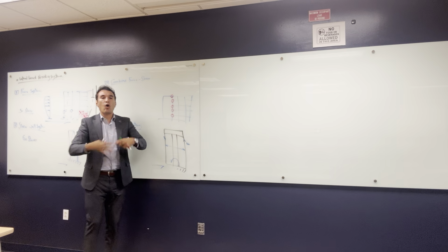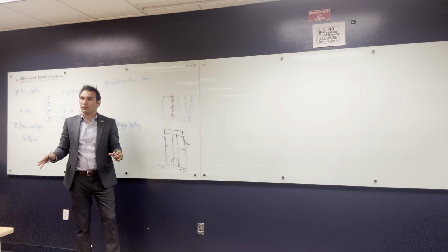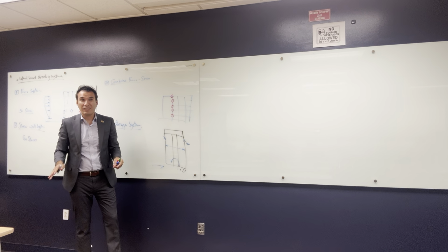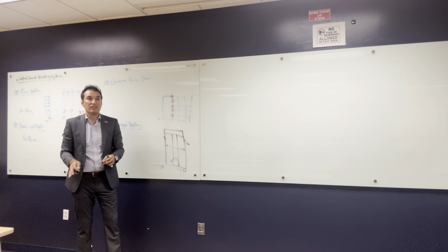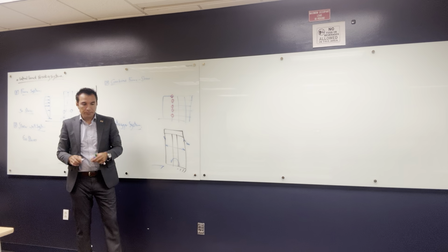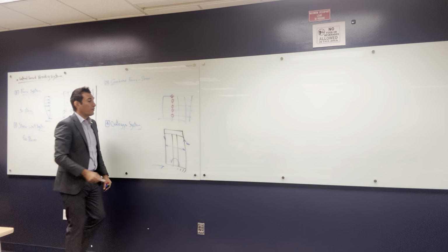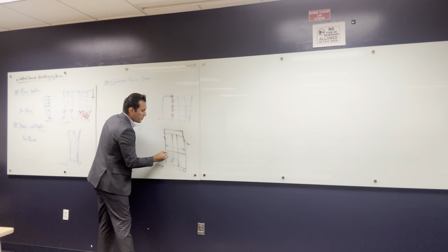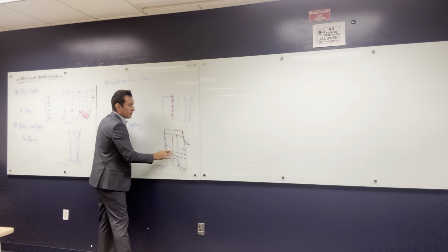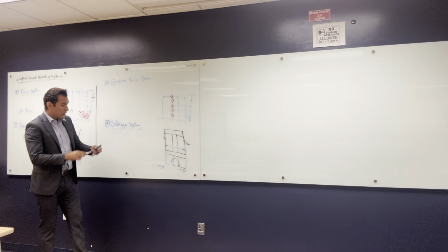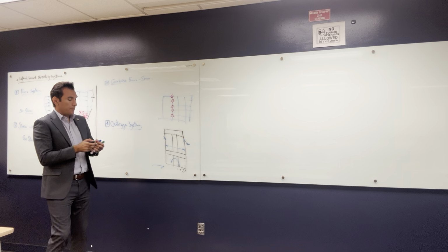So basically the whole story is gonna be an outrigger system. This story, we usually don't use it. We use it for service, like maybe you put chillers for AC, mechanical equipment, stuff like that. Sometimes we need more than one outrigger. Sometimes maybe you need another outrigger here to enhance the performance of the system, okay? And we talked about this last time.